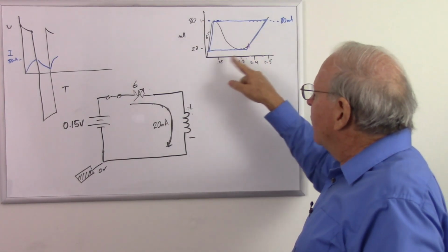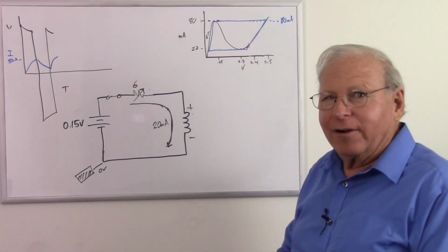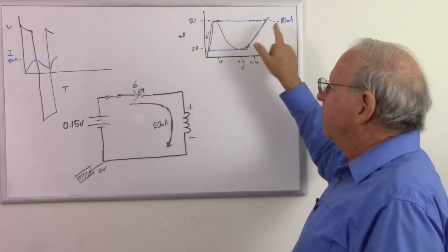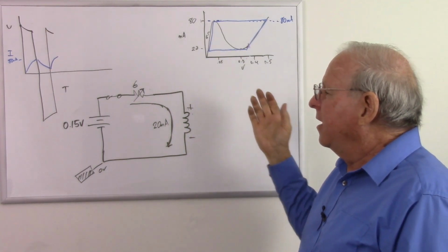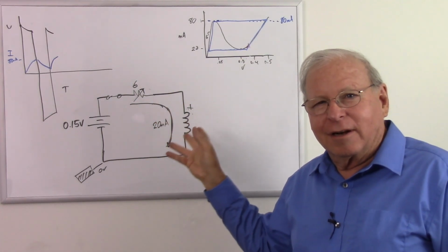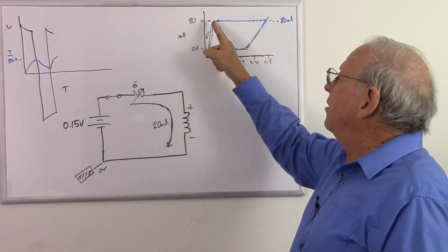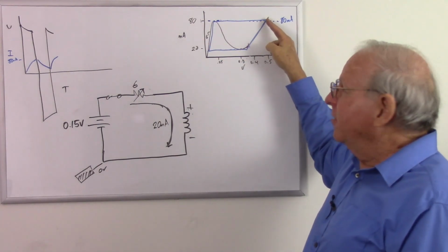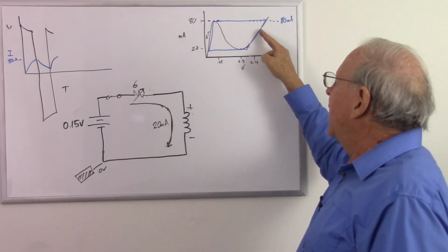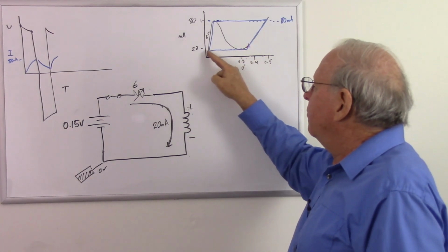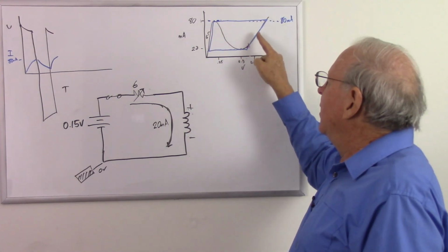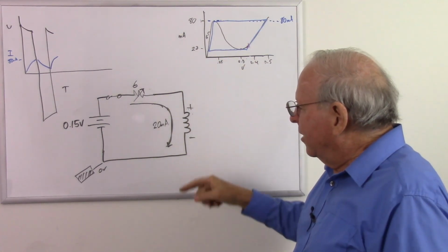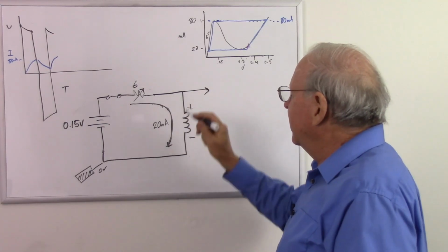So that's why this particular type of tunnel diode oscillator does what it does. It's doing things we can't really fully understand, because why is it jumping from there to there? Well, it has to. We showed that it has to jump. And it's basically just that little green man in the tunnel diode that's changing his resistance to make sure he's somewhere on that curve. So he's on the curve here, jumps over to here because he has to, because the current can't change, but the current can now drop down, but now it can't go up, so he has to jump over here. So now he can go up, now he can go down, now he can go up, now he can go down, and we get that constant oscillation, which we can pick off here as our output,